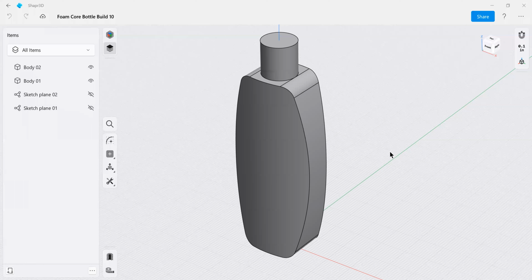Another feature of curving these front and back panels is to prevent an effect called paneling. So in a plastic bottle, it's a relatively flexible material. And if you put your liquid or your material inside, it can cause a flat panel on the front and back to belly out, to kind of curve out irregularly. So as a designer, we want to control that because it can be very unsightly. It doesn't look right, especially if there's material in there that might have gone bad. It looks like something's not right.